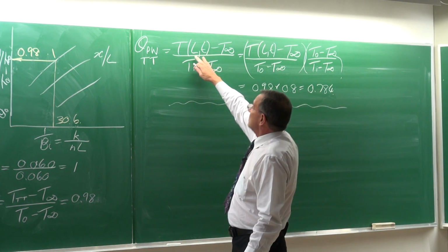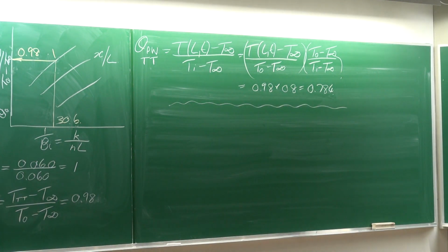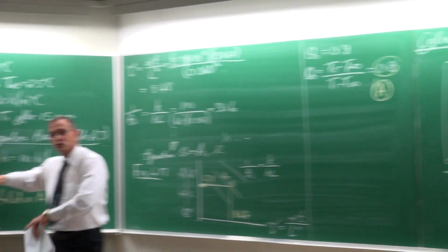Okay, so you can go and calculate that temperature on that level if you want to, but remember that would be the temperature for a plane wall only, at the top.